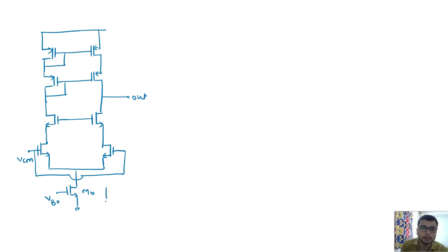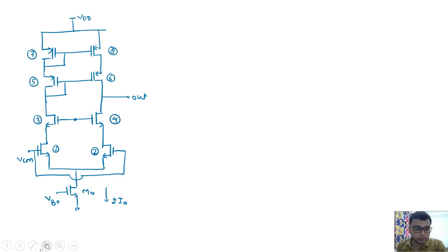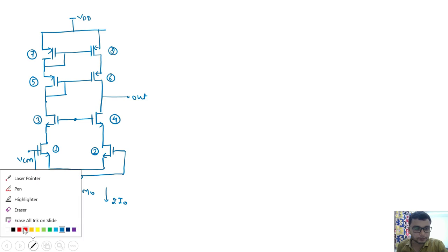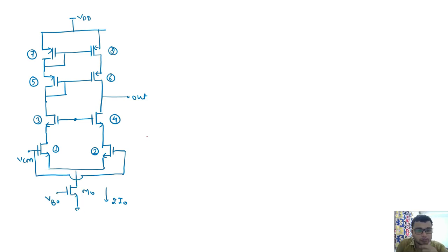I told you that if we are setting I naught, according to that we will set the VB naught, so not a problem. And for this structure, when we calculate the swing and common mode, this voltage I call VB34 is defined from some external source. I am not caring about it. This is a biasing circuit. We will set the VB34. So what is the point now?